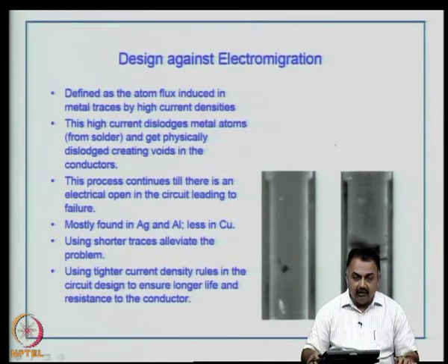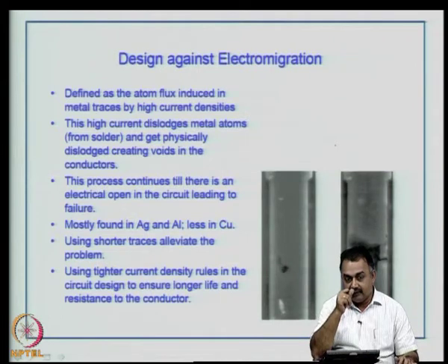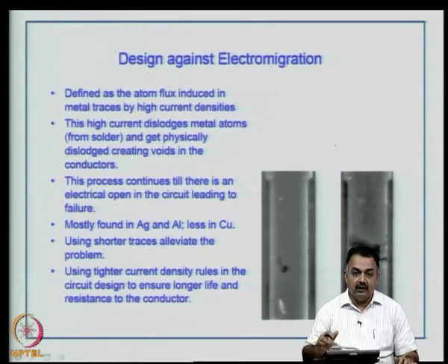These can make a situation where you can have disturbances in the copper in terms of voids or creating what is known as some kind of whiskers in tracks, which can lead to a short due to electromigration, but this is a slow process.